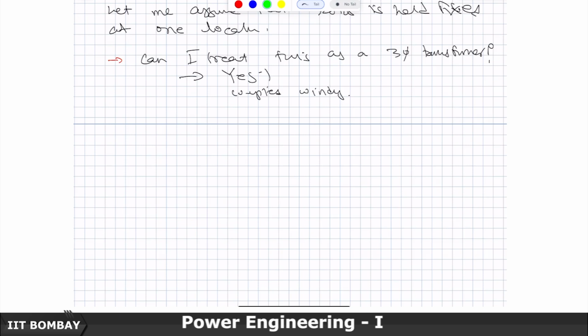But right now, for the sake of our discussion and simplicity, what we have is essentially that the rotor is held still and I have aligned the rotor windings along with the stator windings. So, it looks very similar to three single phase transformers connected to a three phase supply on the primary side and short circuited on the secondary, the three phase windings being star connected and then short circuited.